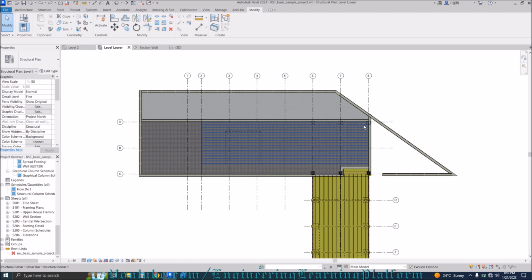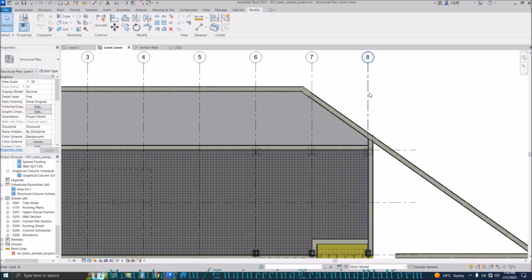OF command is the offset command. Let's press OF and the offset command will be activated. You can offset multiple things at a specified distance. This distance is in the same units which we discussed previously. The units of the distance are specified in millimeters. Let's say I want to shift this wall at an offset distance of 250, and now here we have selected the copy option.